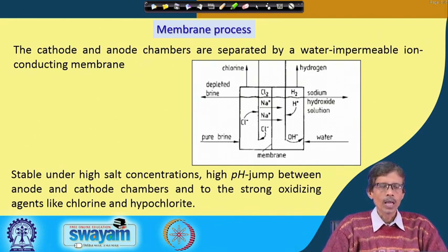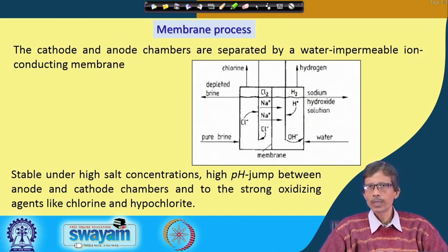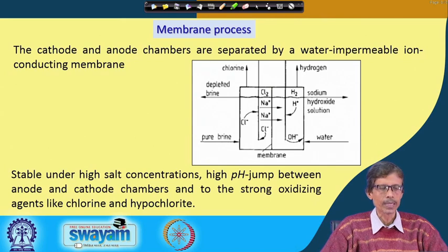important, because you are handling a very highly concentrated sodium chloride solution. So, the concentration of sodium chloride is pretty high. So, the material should be stable under high concentrations. So, your membrane material should be a polymeric one, a polymeric material which will not be attacked by a high salt concentration, and